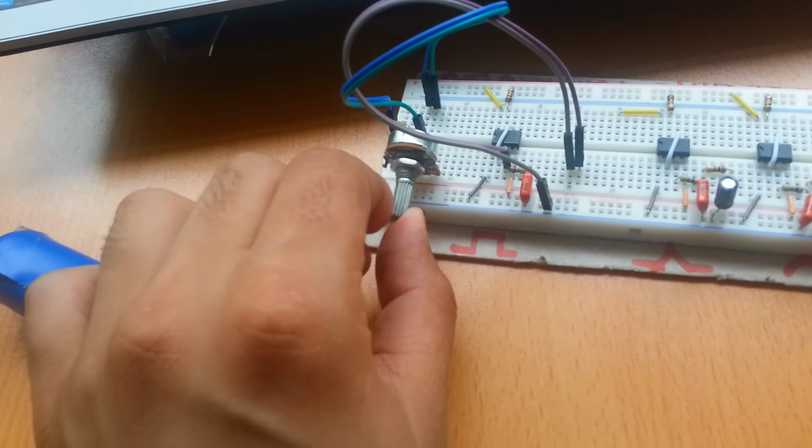Okay, now getting the right voltage, it should be between 4 volts and 13 volts, otherwise the circuit will be burned because it cannot compensate for such voltage. Now, as I said, instead of using a battery, I now have my own voltage immediately from the house electricity. So I put the voltage in the right polarity. We have to pay attention to the polarity, because capacitors, for example, are polar components, and otherwise I will have problems.